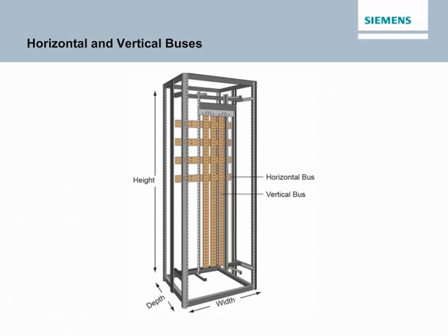Bus bars are made of tin-finished aluminum or silver-finished copper. Bus bars may either be temperature rated or current density rated. The current density rating specifies the maximum current per square inch of a bus bar cross-section.